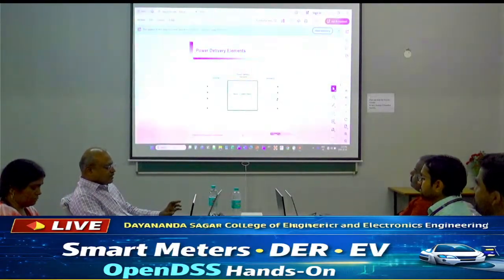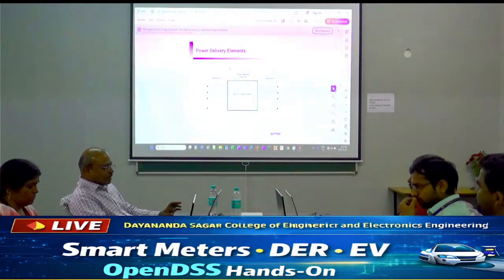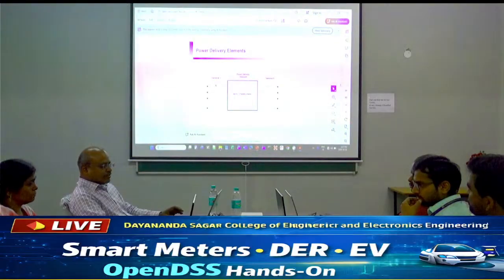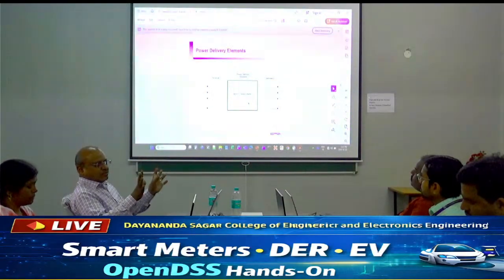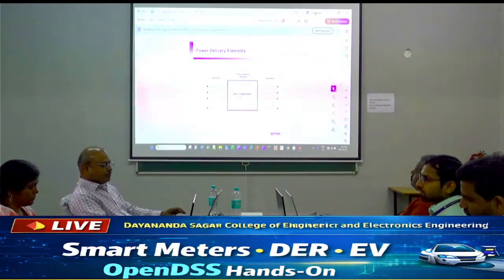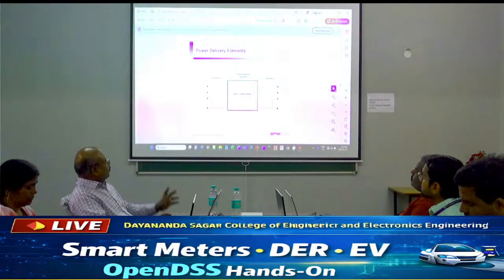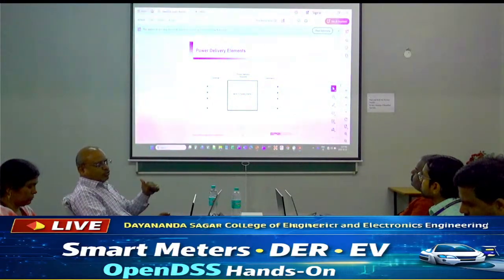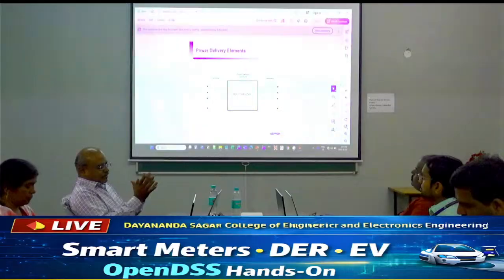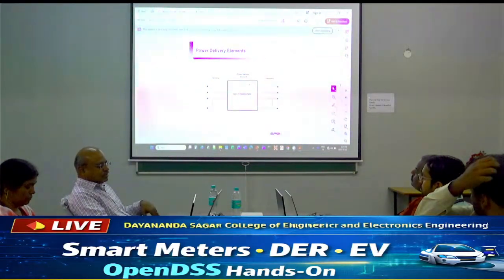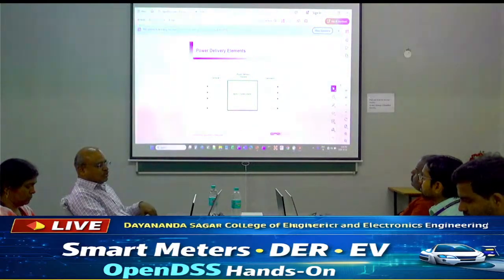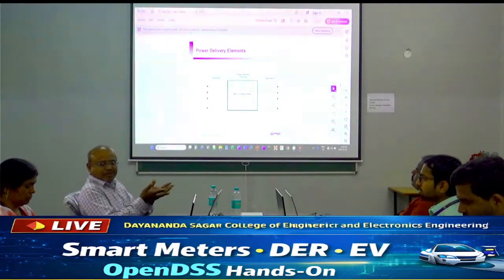Okay. So this is a typical PD element. You will have terminal 1, terminal 2, two sides, and it is modeled as I equal to Y into V. So it's two matrices, the matrix format is what it uses. Basically what OpenDSS does is every element is modeled as a matrix. I equal to Y into V, the admittance matrix.